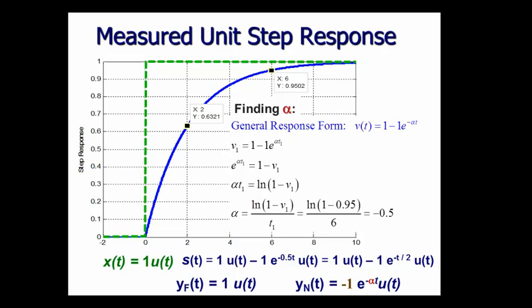We're going to put the pieces all together here. Where am I going to find the roots of the characteristic equation? In the exponent of the natural response. So this has a root of the characteristic equation of s equals -1/2, right? Which would give me this term in the natural response. So that means my characteristic equation must be s plus 1/2.